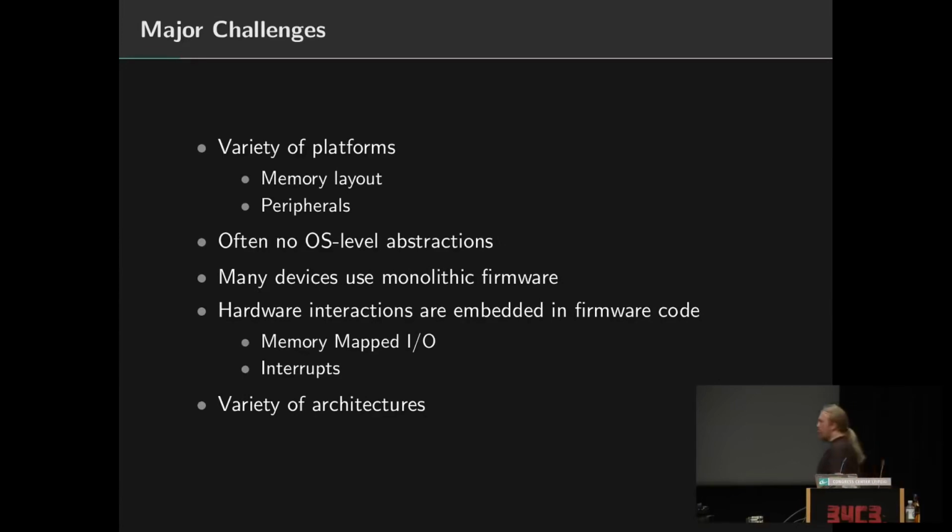However, especially compared to desktop systems, there are a lot of challenges present for firmware analysis. First of all, there is a variety of platforms, a variety of different boards and system on chips, which all come with their own memory layout and their own hardware peripherals, which may be mapped at certain addresses and may behave completely differently on other devices.